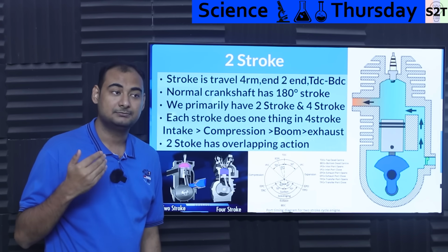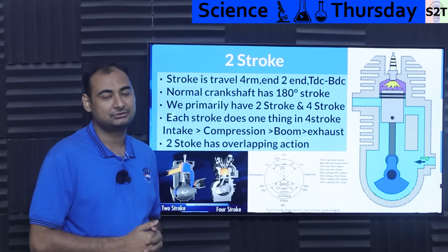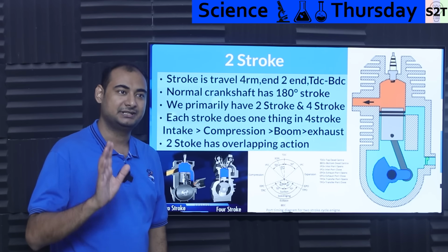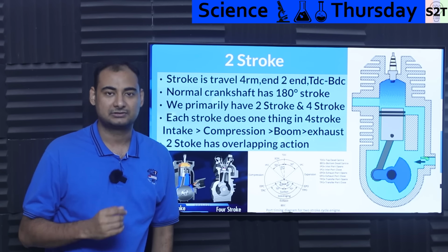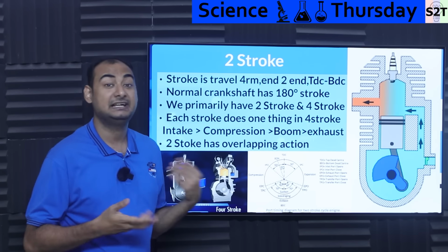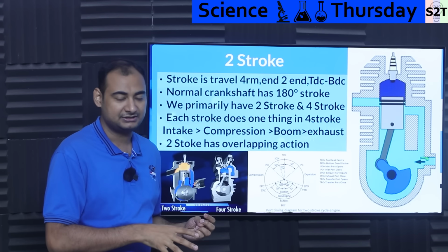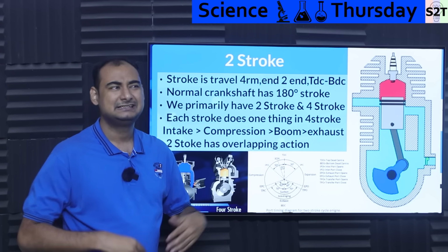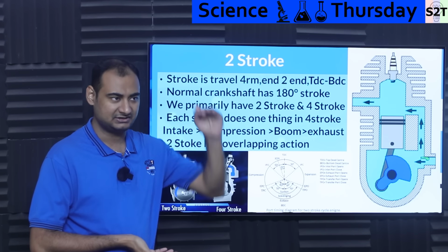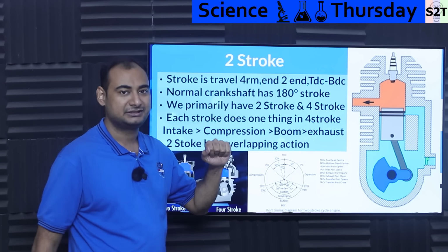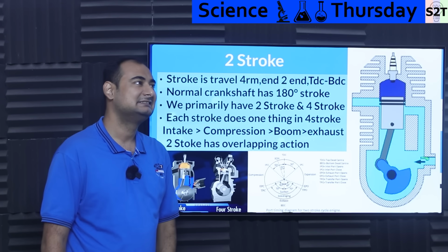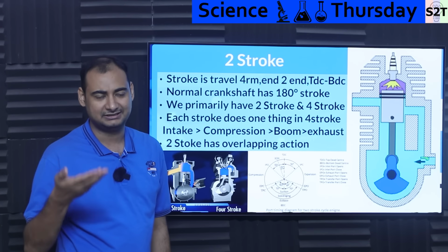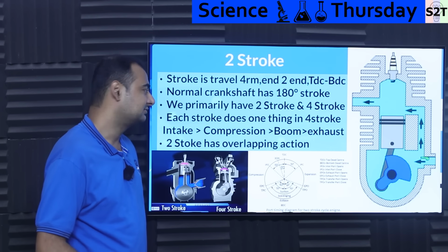Now there are other mechanisms. Porsche is trying to do something very weird where they have a marriage between four stroke and two stroke, making a six stroke system. There are other people who are also claiming a six stroke system where something else is going on. For example, you could have water injection into the cylinder to cool it down, and it basically expands and vents out. It just adds a pseudo power stroke. Basically you have one power stroke that gives you, let's say, 1 kilowatt of energy. This water injection that becomes steam gives you one mild power stroke, so let's say 1 kilowatt, and this will be 300 watts maybe. So those will be six strokes.